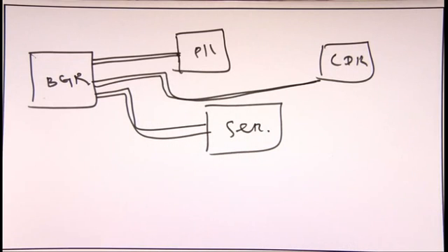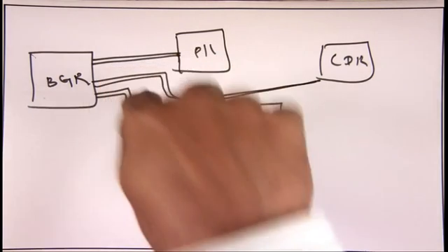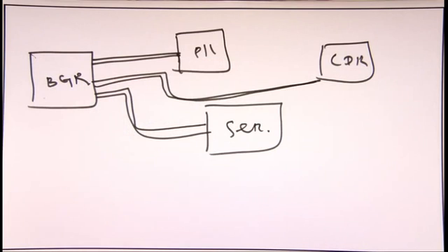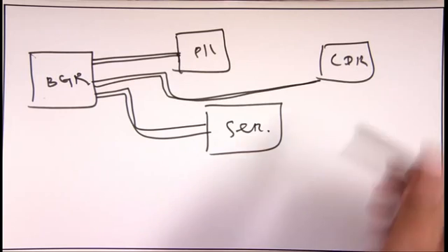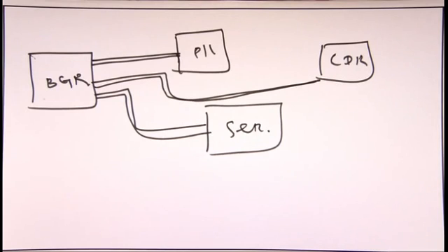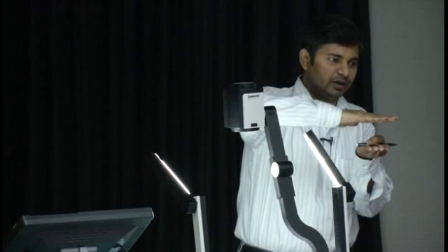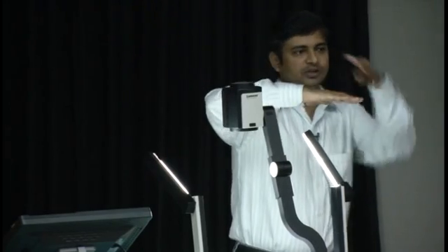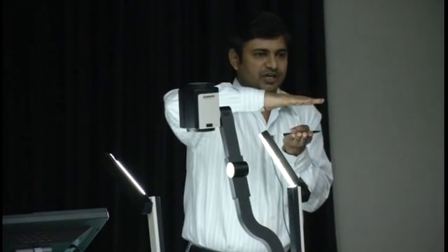So what happens, suppose any noise comes into this line, then it will create some problem in sensitive blocks like PLL and CDR. So that's why we will do some 3D shielding. What is 3D shielding? Generally we use metal 1, metal 2, metal 3 for 3D shielding in power routing. So what we will do, the connection should be in metal 2, with metal 1 below that metal 2 and metal 3 over that metal 2. This is one type of shielding.